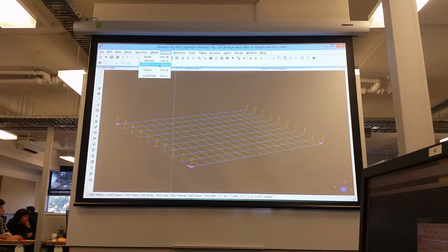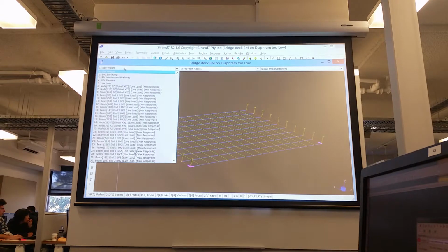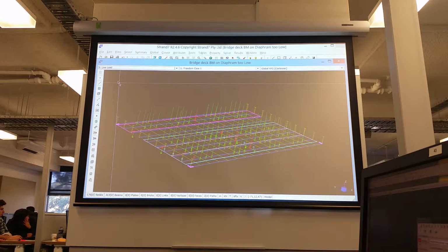The other point was that the position of the response variable. So let's just go to the live load case, and for the end diaphragms, for the first run we did, the response variables for moment and shear were set up on that position here. So when the computer generates the load position to get the maximum bending moment, it would actually find a position that gives the maximum bending moment at that location. But that's not necessarily the maximum bending moment anywhere along the end diaphragm.